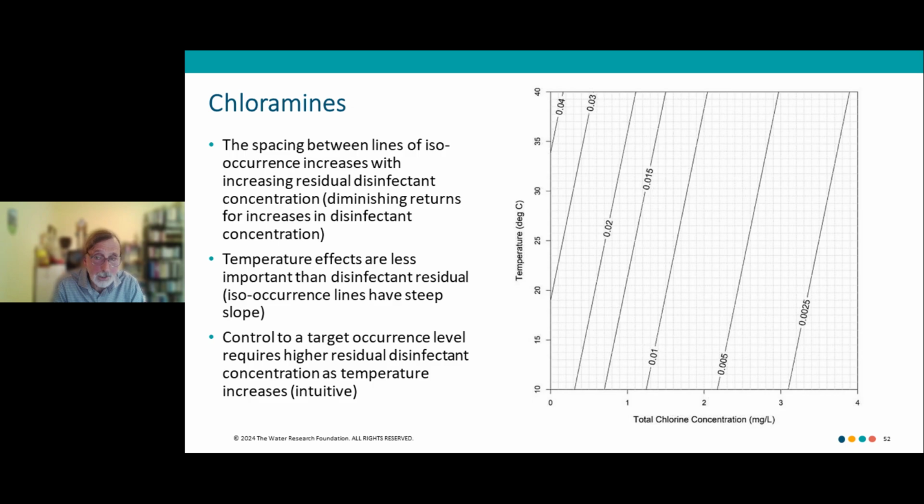That is, just like the free chlorine systems, there are diminishing returns as you increase the total chlorine concentration. And that's because you're treating something that is not the root cause. You're adding total chlorine when in fact it's something else that is harboring and causing the Legionella to grow. Temperature effects are less important than disinfectant residual.